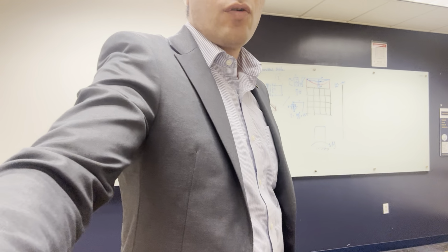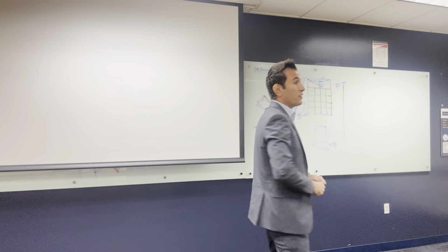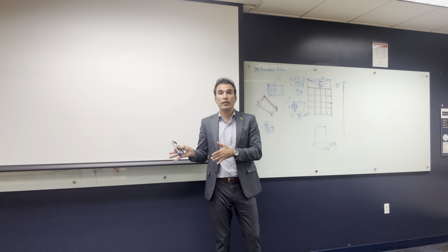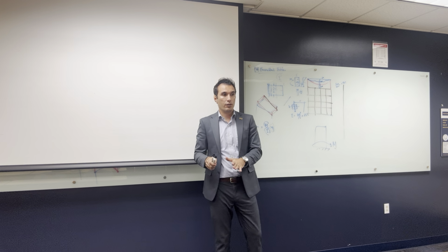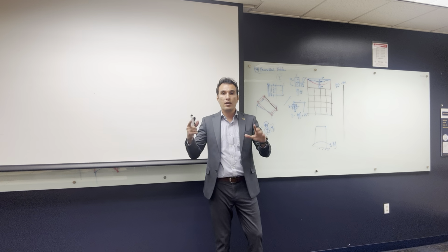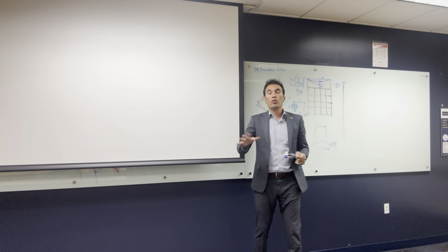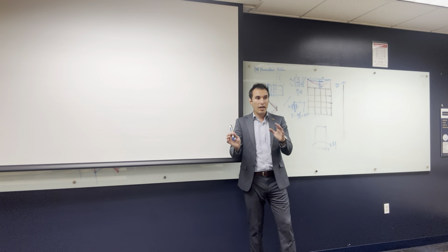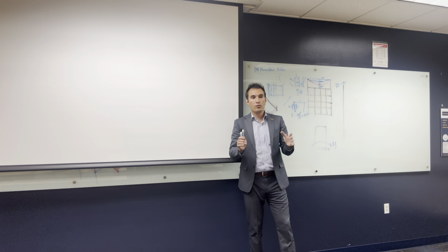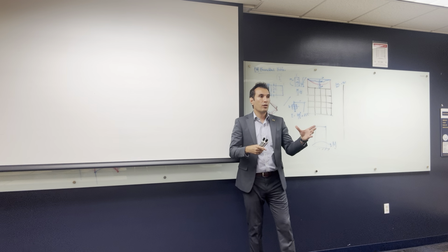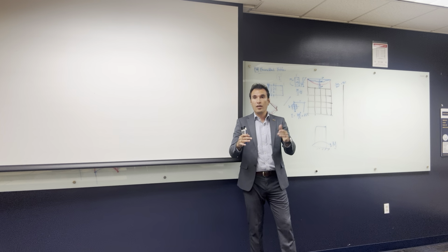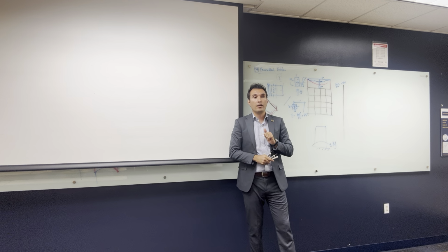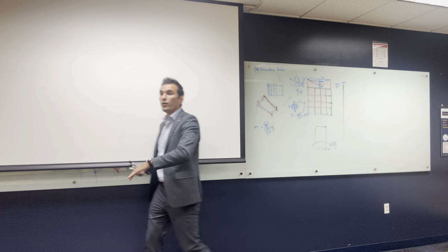Okay. So our project is going to be a 60-story rectangular building. It's going to be a tube-in-tube system. I'm going to provide you the layout. All of you are going to have the same project, 60 stories, same outside dimensions, but each one of you is going to do what we call a parametric study. So you're going to have the same building. Some of you are going to use column dimensions of 1 meter by 1 meter. I'm going to provide a table for each group. Some others are going to use columns 1.5 by 1.5, and some of you are going to use different beam dimensions.